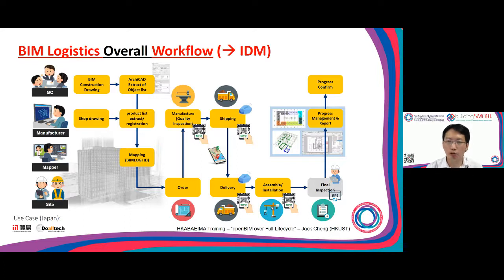And then based on this workflow, they have not achieved it yet, but what they are working on now is converting this into the IDM format. If you remember, we talked about IDM. Basically, we have the workflow and also the exchange requirement. So once they define the workflow, then for each step, they define what the exchange requirement is. This is basically the concept of IDM.